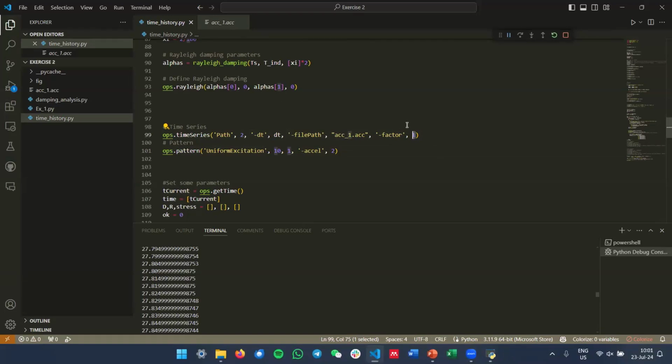Check before running the analysis. Check what your input is. Otherwise, you will start to have problems that you don't understand, and it's just, I don't know, one missing number, or a letter somewhere inside your input, stuff like that. It happens. Or just an order of magnitude, one acceleration that is higher because you changed the scientific notation factor. So check the ground motion before running it.